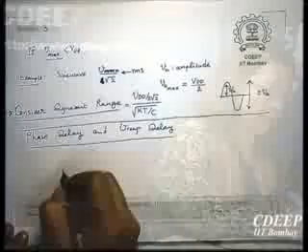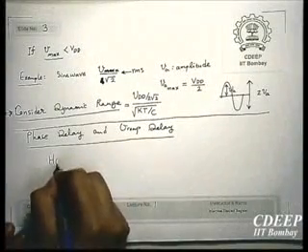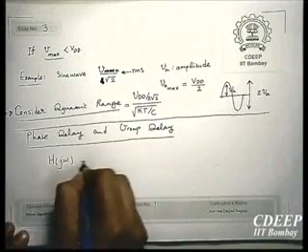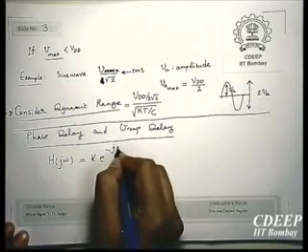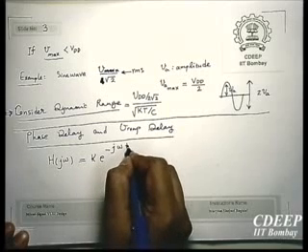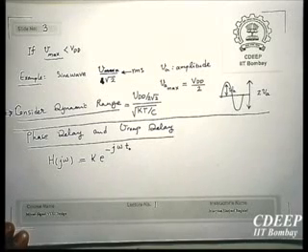And that's why we have the concept of group delay. Group means a group of frequencies, and delay for a group of frequencies should be the same. Therefore, group delay is important. So, for example, say we have just a simple transfer function like that. Suppose I have H(j omega) equal to k times e to the power minus j omega t0.